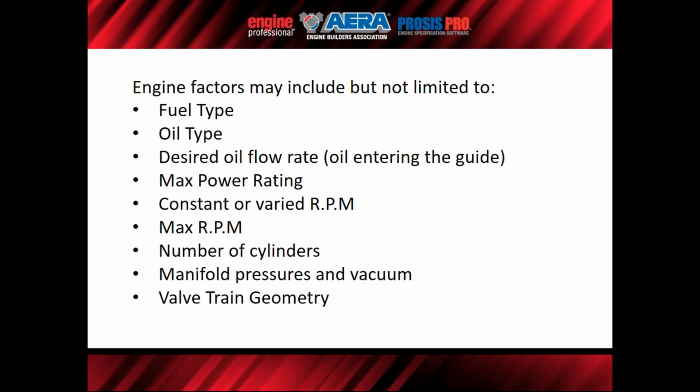Engine factors that can be included, but may not be limited to, the seal design. Of course, fuel type, oil type. For propane and natural gas applications, you're not going to use the same oil that you're going to use in a diesel, which is not going to be the same that you're going to use in your gasoline passenger car. There is some crossover. If you have a multi-fuel engine, maybe you've got a CNG application, and you run gas when you have it, or gasoline, and you switch back and forth, you're going to use some multi-grade oils there.